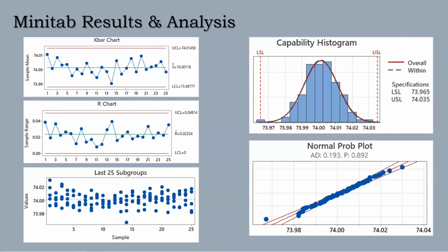And then if we actually look at the normal curve they give us here, we are seeing that the red line and the dashed black line are basically the same. So we can say that the variation in the process overall and the variation of the process for each subgroup are basically the same. There is not much of a difference in their spreads, or in their standard deviations. One's not steeper or smaller in the middle than the other. They lie pretty much on top of one another.